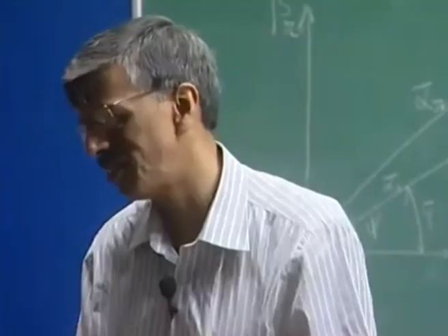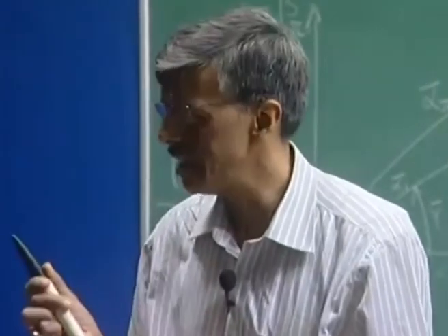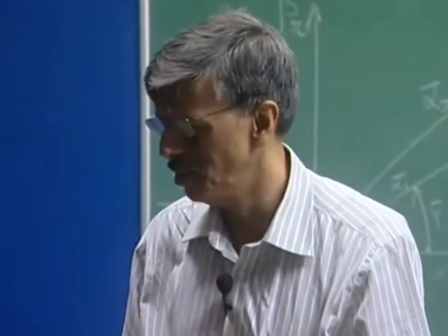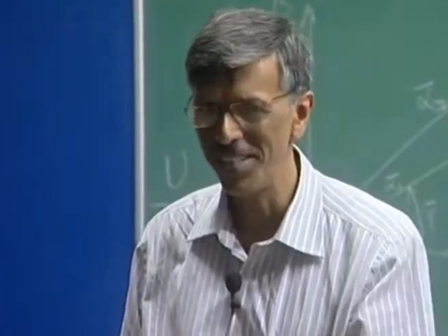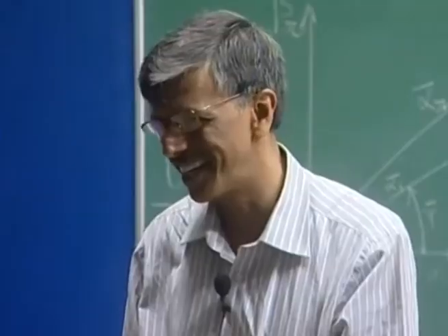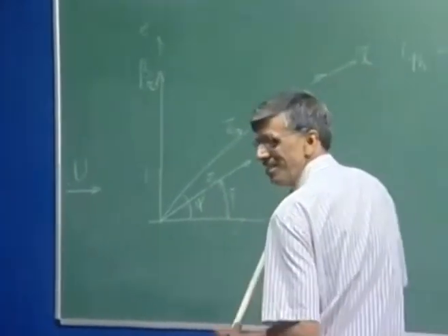You will see all kinds of disturbance, and the better thing to do is set up an experiment. You put some kind of exciter on the wing, a point exciter, let us say a mechanical vibrator, and vibrate it, and from that single point disturbances will come out in 3 dimensions, and there you will see all these nice things.